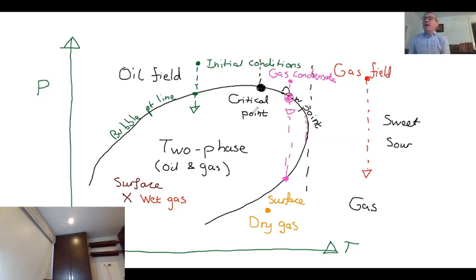And what is the undesirable thing that is in the oil or gas is H2S, hydrogen sulfide. And H2S is highly toxic. You can't sell gas containing this, any H2S. So that H2S has to be separated out from the gas stream. And it's exactly the same as what you have to do with CO2. If there's CO2 present, you have to separate that from the gas stream.